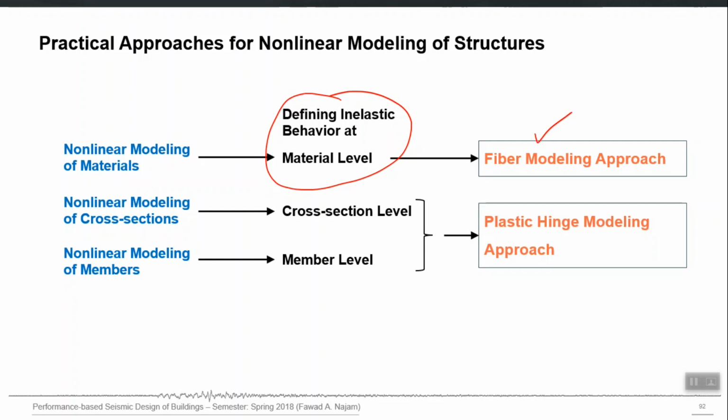And when I say nonlinear curve, please keep in mind that it is not just the backbone curve, it is also the cyclic behavior, how the material will behave in one go, or also how it will behave if I give cycles of loading, unloading and reloading.